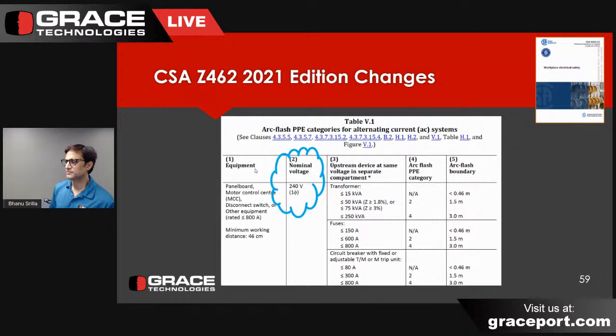But you'll notice for the single phase, if the transformer is between 75 and 250 kVA, it says we need an arc flash suit to work on a panel board. 120 single phase, 240 single phase. And if you actually poll every electrician in North America, which will be hundreds of thousands, if not millions, they're going to tell you they've never experienced an arc flash on a 120, 240-volt single-phase panel board. Arcing faults, yes. The melting of the screwdriver shaft before they taped it up with electrician's tape because they didn't want to buy expensive insulated hand tools. But there's been no arc flashes.